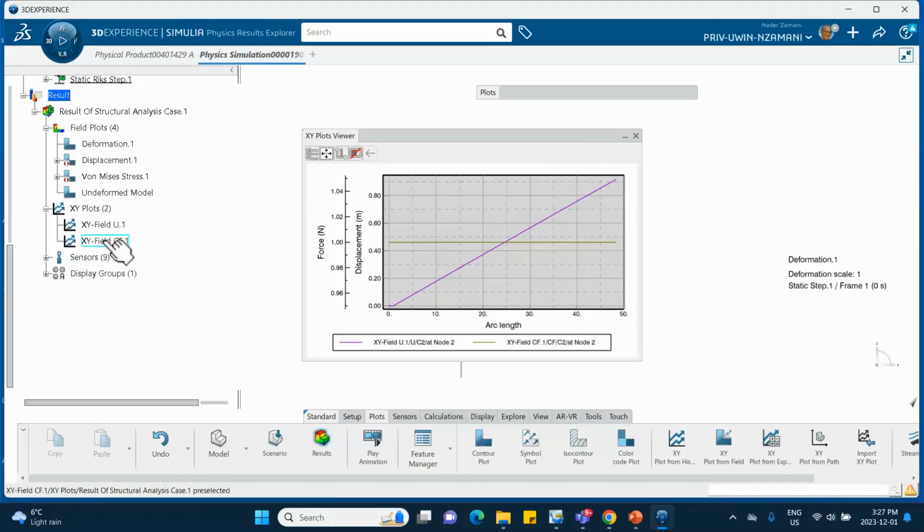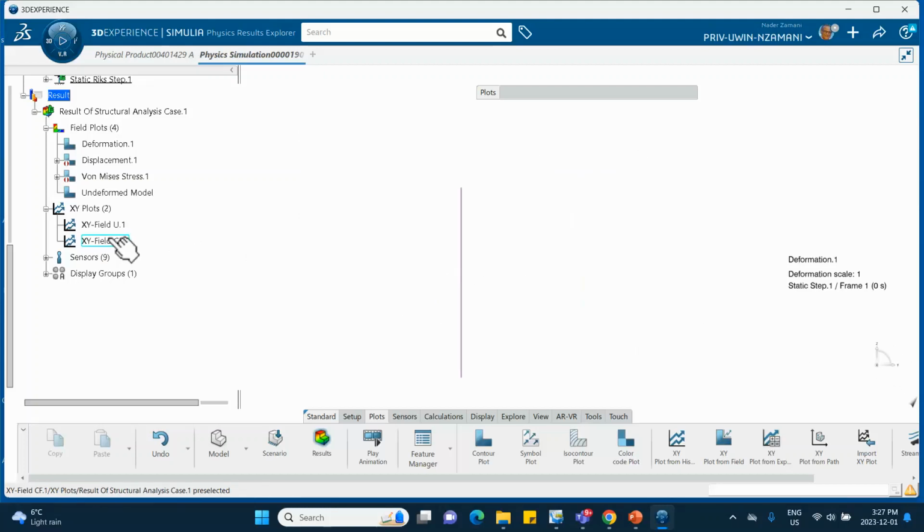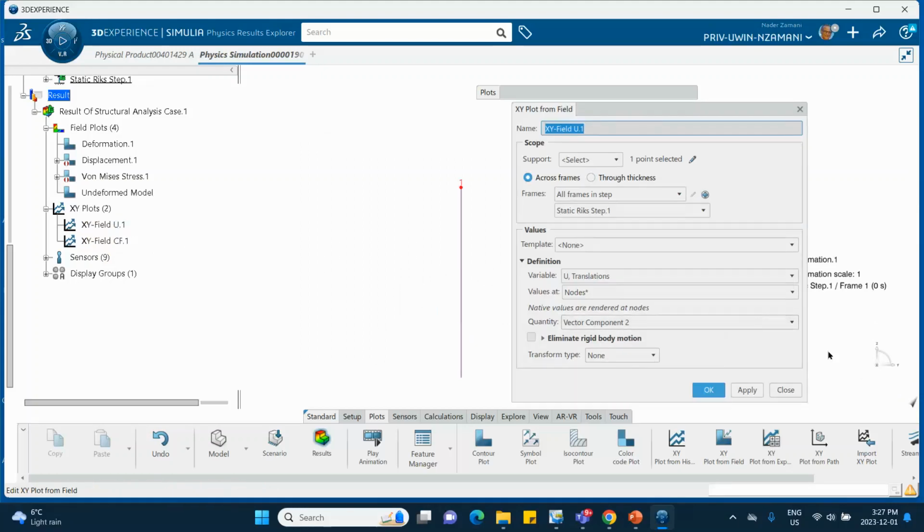this should be downward. I took it in the direction 2. Let me see for a second. Let's see how we did this thing. Let me go and double click on this. This is direction 2, direction Y. The question is, I don't want direction Y. I want direction 3, because that's what I'm saying. The choice of those selections in the YouTube video on ABAQUS CAE may not have been quite what he wanted. So I changed this thing to component 3, downward.